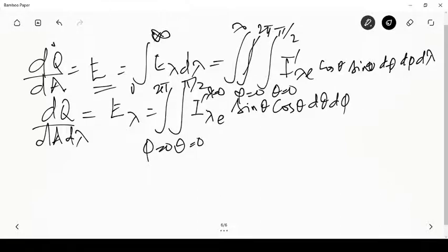So if you want to find out the emissive power of any surface which is a general emitter which has variation in spectrum as well as direction, then you need to define its intensity as a function of theta, phi and lambda, and then integrate it over all of these quantities in order to get the emissive power. So this is something which is inconvenient, complex, and so we would like to find easier ways of doing it. So wherever it is possible, we try to make approximations of when the surface can be treated as gray or diffuse, or at least piecewise gray, piecewise diffuse.